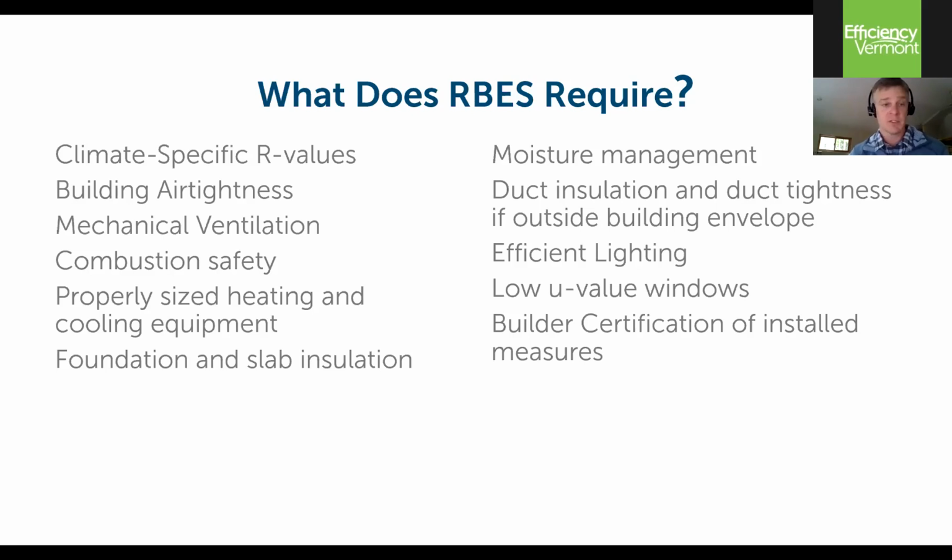So combustion safety is a big part of this. Properly sizing heating and cooling equipment. Oversized equipment has a huge energy penalty, a huge cost penalty, and a durability penalty as well. So, making sure that the equipment that's being installed in buildings to heat and cool them is appropriately matched to the needs of the building is important.